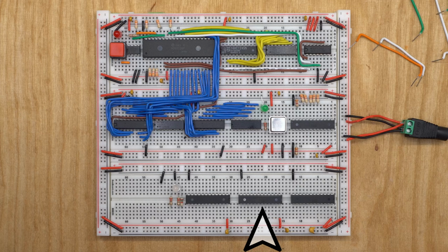And that's I/O decode. Finally, the last PLD is another ATF22V10 handling shadow ROM control, splitting the read-write line into clean read and write signals, and displaying the CPU speed in real time. This one is Shadow Plus, because miscellaneous but important doesn't fit on a label.